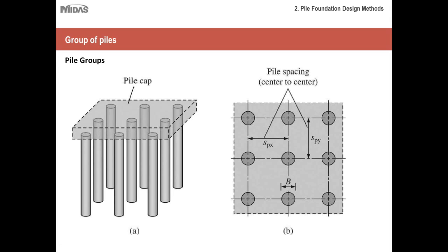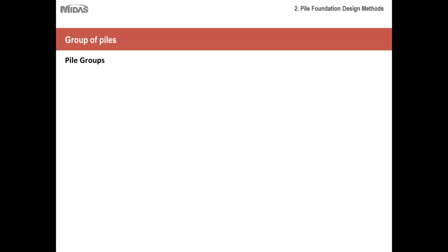And for getting this pile layout correct or optimizing this group effect, what we have to really work out is what is the optimal layout of the pile. What diameter of pile should I use in this group? What should be the thickness of my pile cap? There are so many variables that you have to really work with in order to optimize the group behavior of the pile.